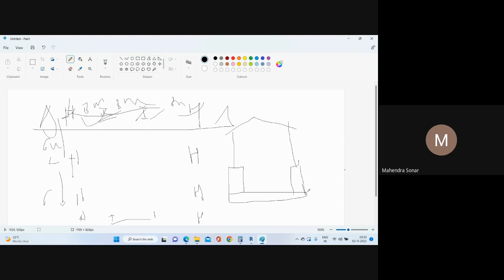Okay, so you need to give the levels. So first level is your top of slab, then top of column, right? Then here you can give top of steel column, right? And roof. So you need to add these levels, whatever you have designed. Okay, the distance. So let's start.